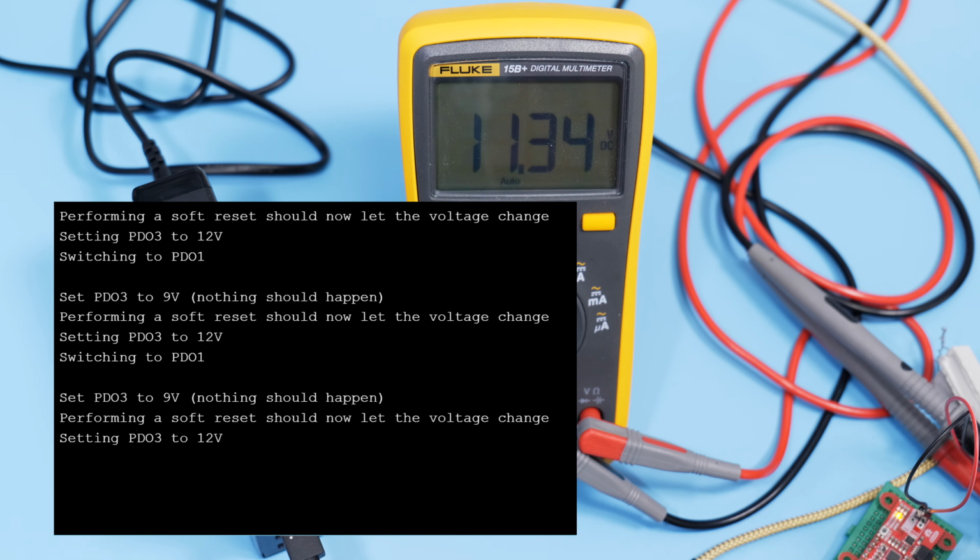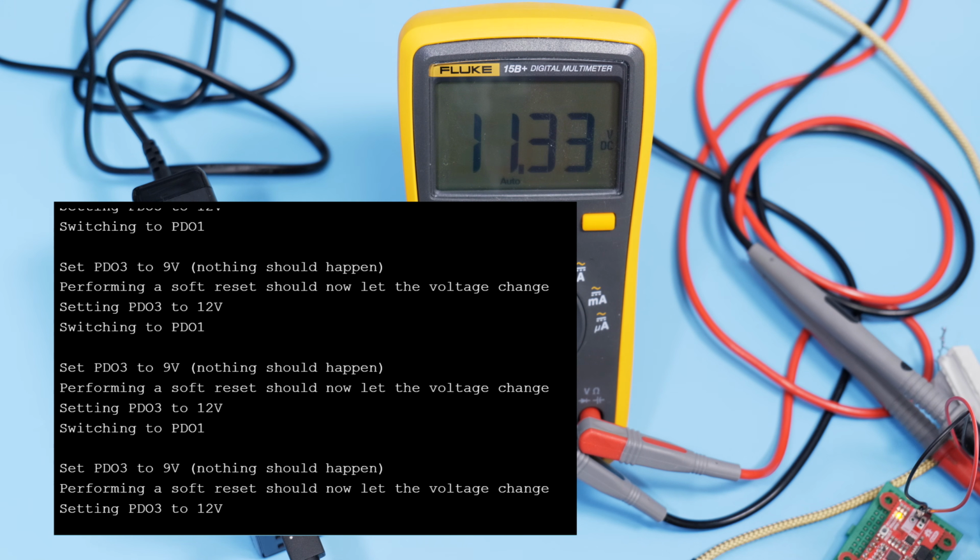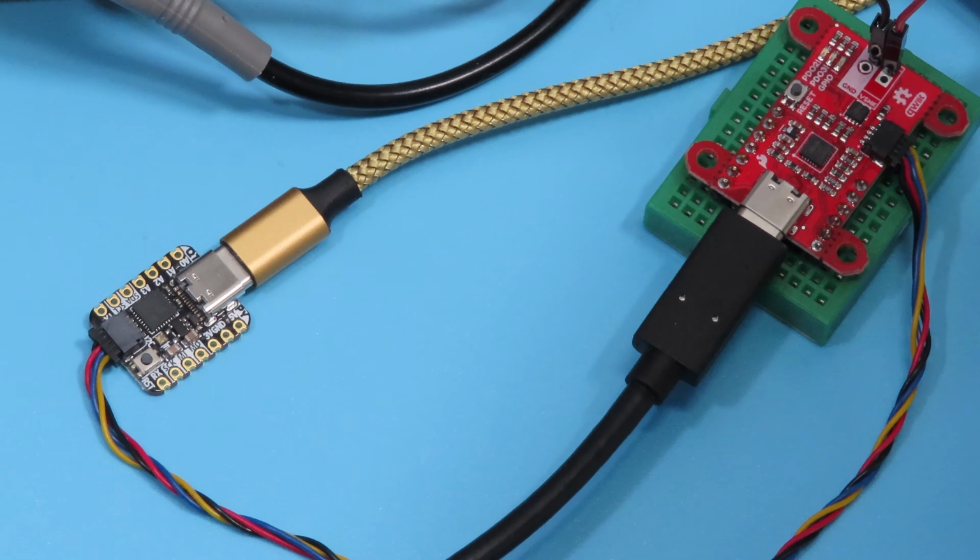Now, obviously, this is a pretty sophisticated board. It's much more expensive than the other ones we've looked at. I wouldn't use it for every application, but the PDOs make it possible for you to set different profiles for power and have your device act differently depending on the USB-PD adapter that it's connected to. If the adapter doesn't have all of the features, you can switch to a different voltage and perhaps perform a different function. So it's a very versatile board for those who need that kind of versatility.